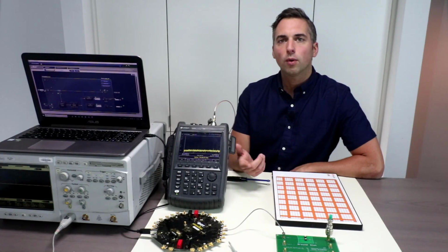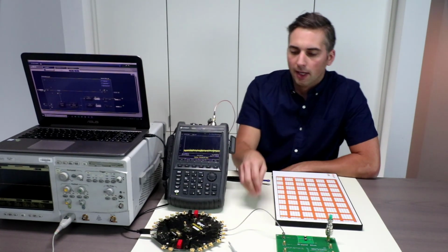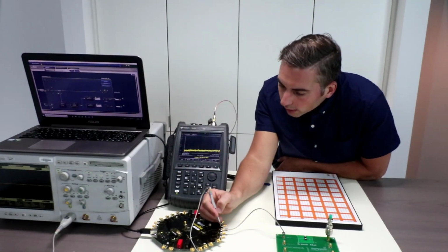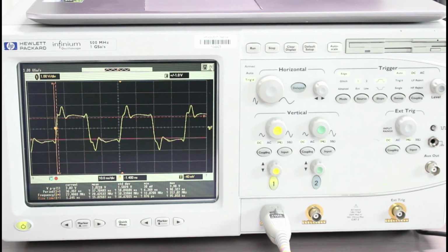Alright, demo time. So what we have here is a clock source from IDT, that's this board. And if I connect up a scope probe here, we can see on the scope that in the time domain it's a clock and it's set to 25 megahertz. Now there is some overshoot and undershoot which is likely a result of the impedance mismatch from the load plus also the current loop that I've intentionally put in this circuit, which we're gonna be looking at.